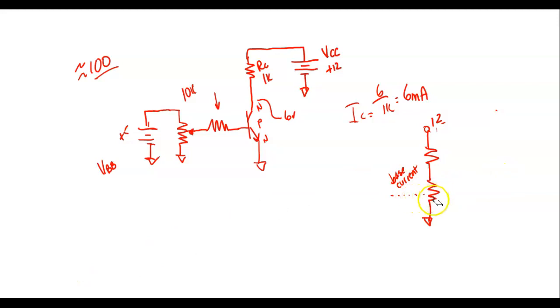So if I increase the base current, this resistance goes down, which means the transistor drops less voltage and the resistor drops more. If I decrease my base current, then my transistor drops more voltage, which means my other resistors have to drop less because of Kirchhoff's law, right? You understand that? So if you can look at the transistor as this, then you got it.